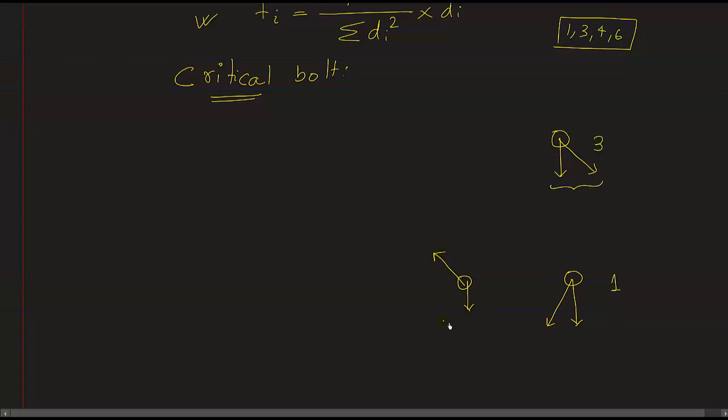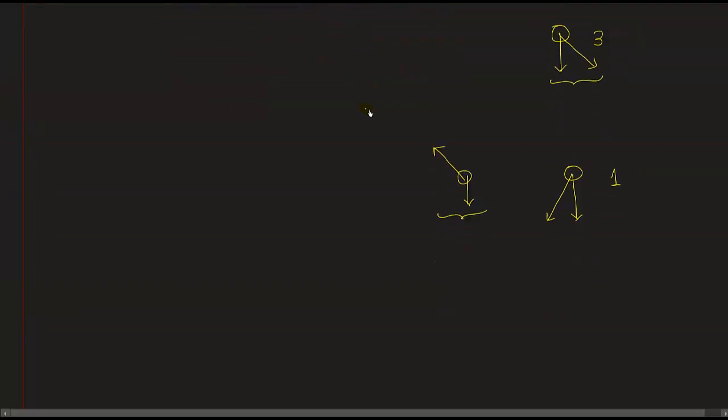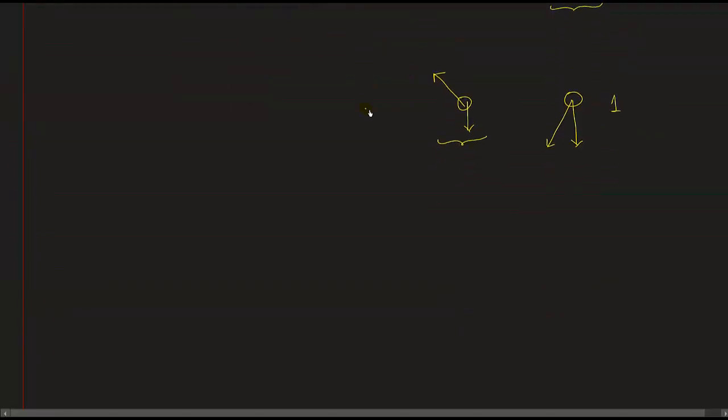So they are cancelling in nature. So these two forces will subtract. So I can say either bolt 1 or bolt 3, these two bolts are the critical bolts. So critical bolts are 1 and 3. In this case both bolts will have the same force. So let us calculate for bolt number 3 the total amount of force that will be generated. So I can draw this.